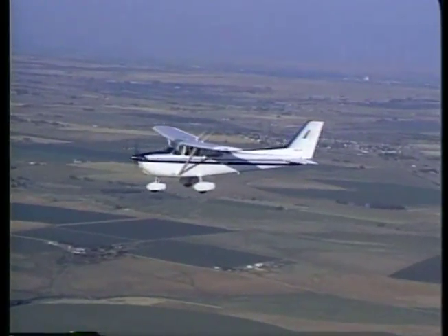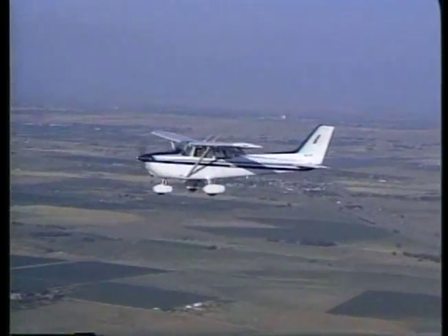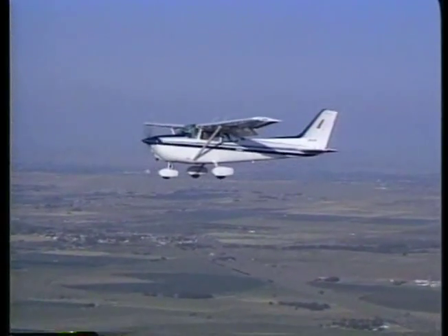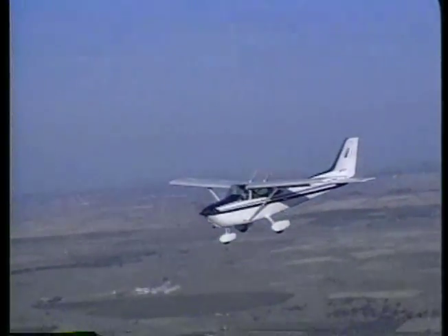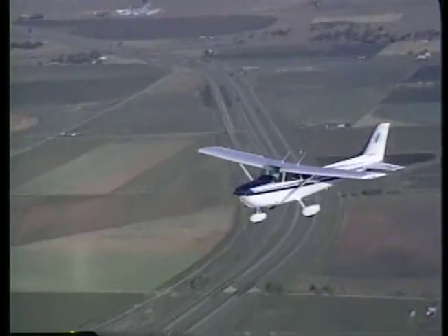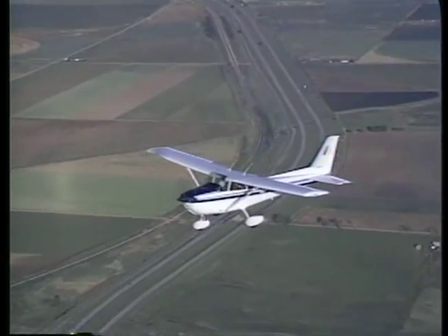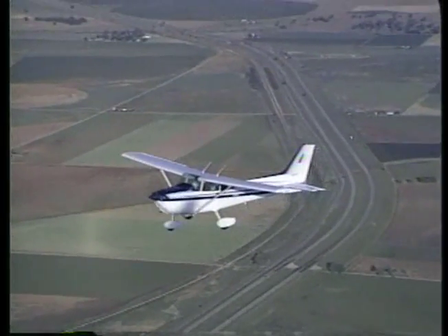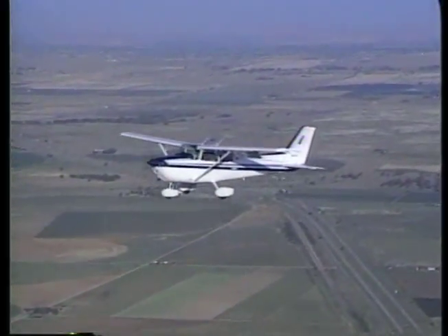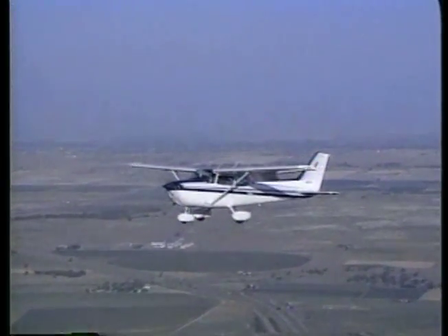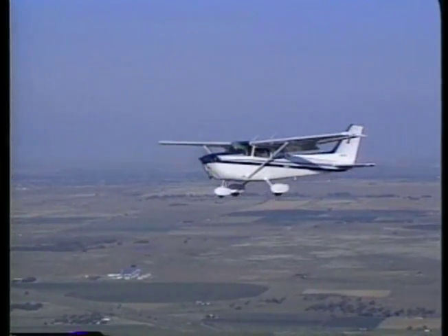When maneuvering during slow flight, you are flying very near the stall speed of the airplane. But you don't necessarily have to be flying at slow airspeeds for a stall to occur. A stall can happen at any airspeed and in any flight attitude. This program will explain how to recognize an approaching stall with the power off and the procedures for recovering from a power off stall.